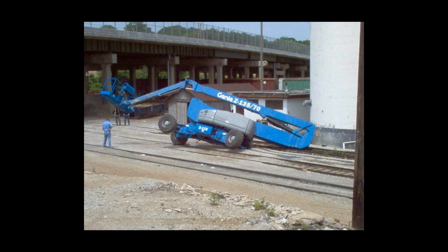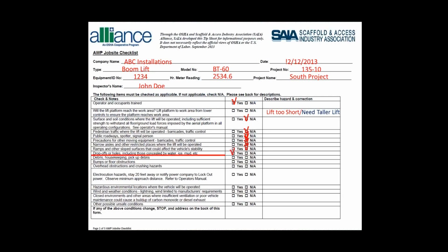So we would have identified this hole prior to operating the machine. And I'm going to say now we have a hazard, we have a service cover, the hazard is the hole, the risk is the machine could tip over or potentially cause ejection. So we need to mark and avoid that hole. But we also need to pay attention throughout the usage of the platform that now that we've marked that hole, we need to make sure that we don't drive into it. Again, the ongoing workplace inspection.